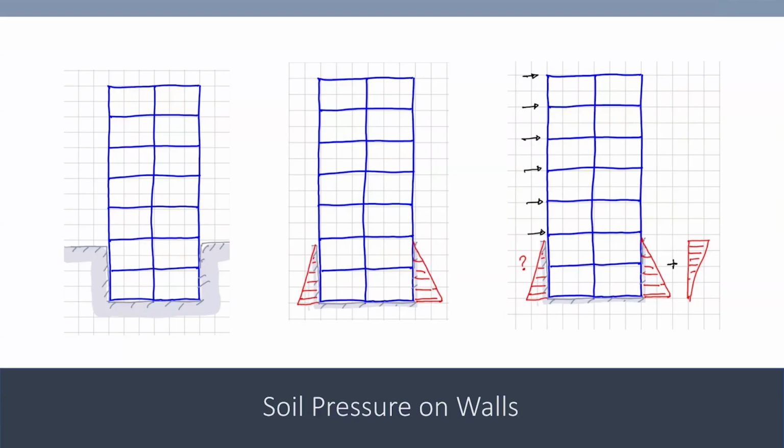So in both directions, you might have soil separation between the structure and the soil, and you also will have excessive pressure. The pressure generated on this side will be the inverse of the triangle pressure, because at the top it will push more, and as you go down the push will be less, so pressure will be less. That means the increased extra pressure, where initially it was zero, will be large. So now suddenly you have a very different soil pressure profile because of the lateral movement or lateral forces on the structure. So that's the first thing that we need to know.